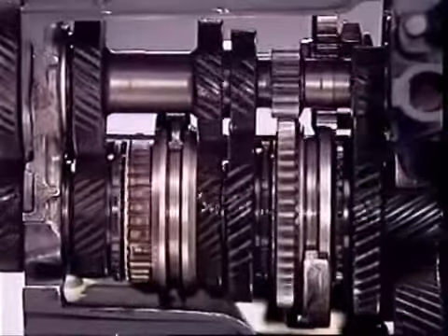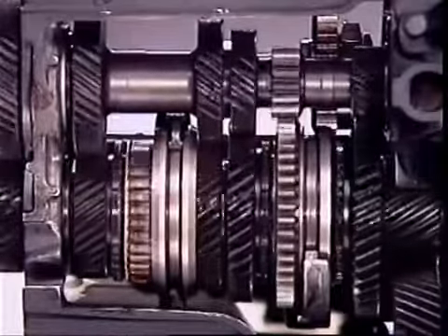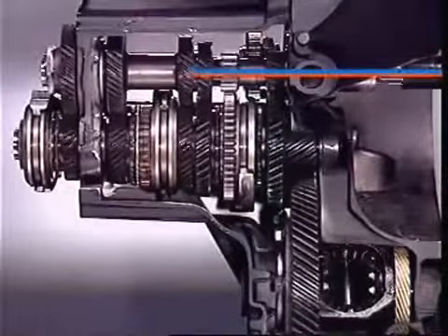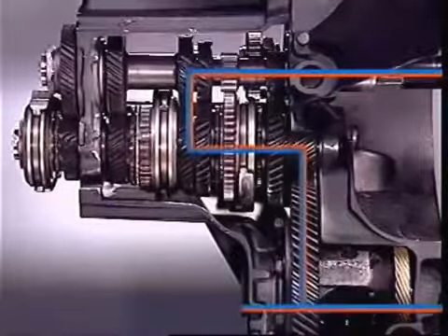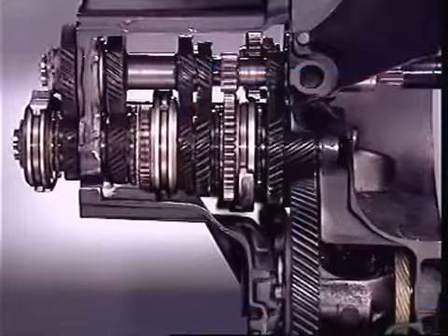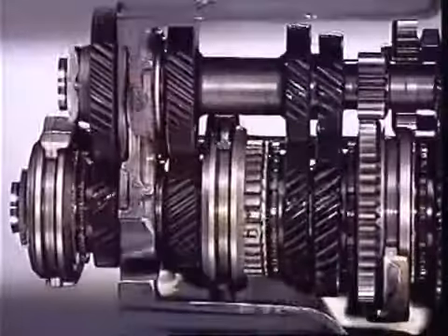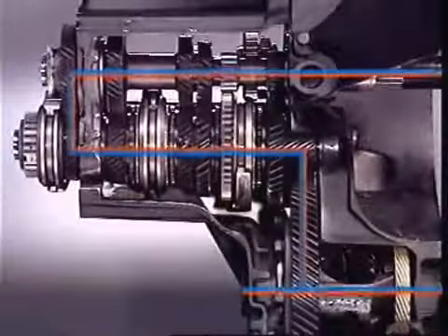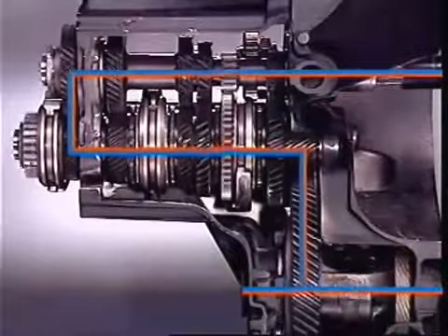In third gear, the engagement sleeve locks the freely rotating third gear to the secondary shaft. Drive is transferred from the fixed gear on the primary shaft to the locked gear on the secondary, and then to the final drive. The drive transfer is similar for fourth gear. The 5th gear ratio is provided by transferring the drive through the fixed 5th gear on the primary shaft to the engaged fifth gear on the secondary shaft.